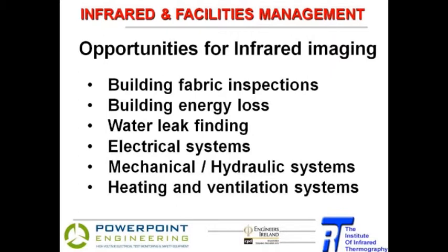With facilities management, there's lots of opportunities for using infrared. Building fabric inspections, energy loss, leak finding, typically water leaks, but it can be other things as well. But more often we're looking for water leaks. We can look at electrical systems, mechanical, hydraulic, and heating and ventilation systems.